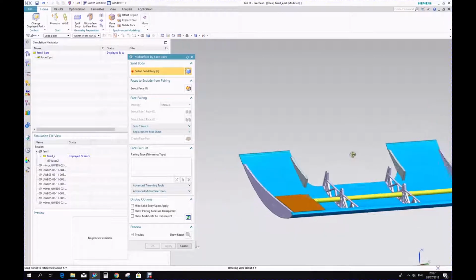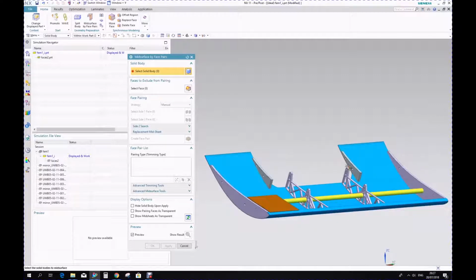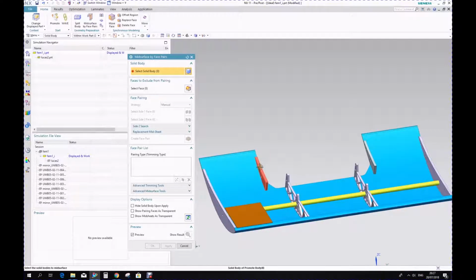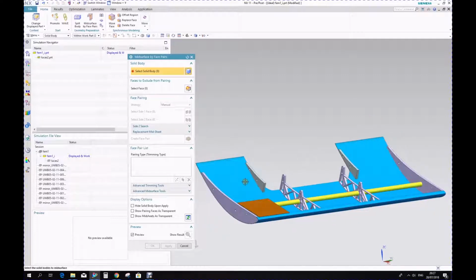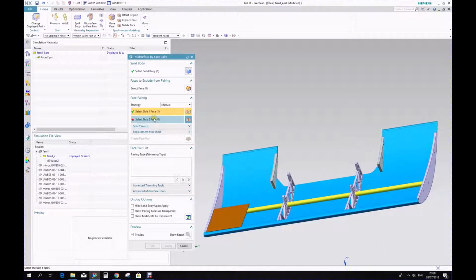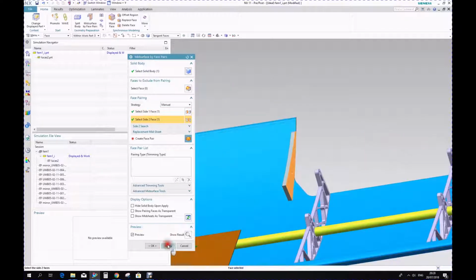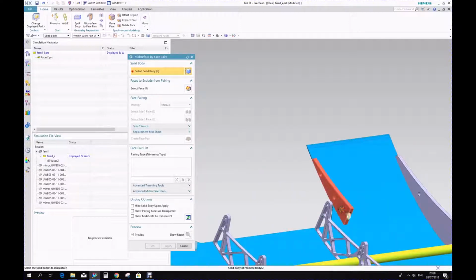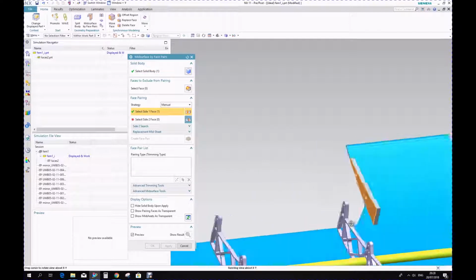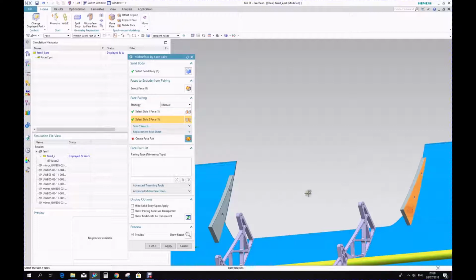If your part file is already a 2D part, we don't need to do it inside the FEM. We can export directly from your CAD. So we want this body, this face, this one, apply. Same for this body. Select this face, select that one, and apply.